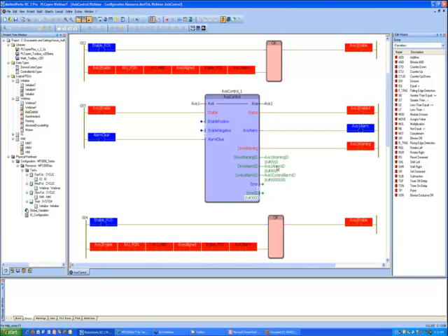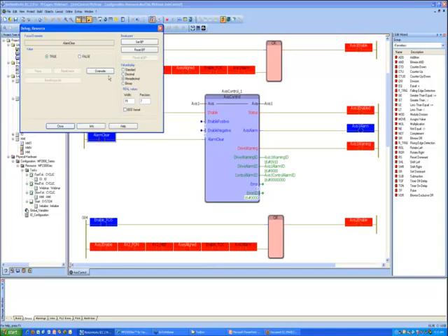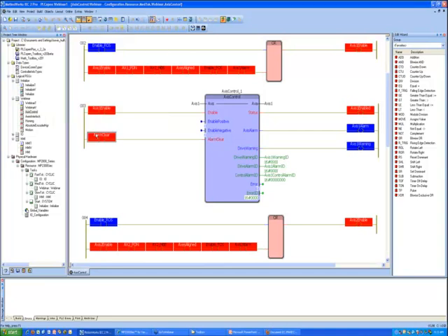And this was caused by actually clamping the motor so it could not rotate just a moment ago. I can clear that warning by doing the alarm clear input. And now that's cleared out. You can also see the status. This is a direct copy of the status output from MC Power. And that's basically what the access control function block does. It's a 3-in-1 block, basically, that allows you to enable and clear alarms in one.